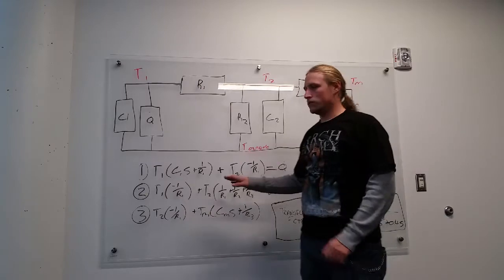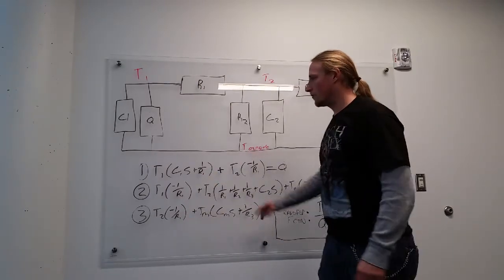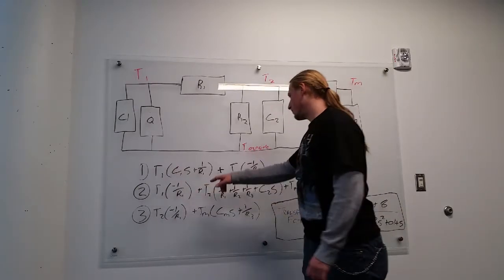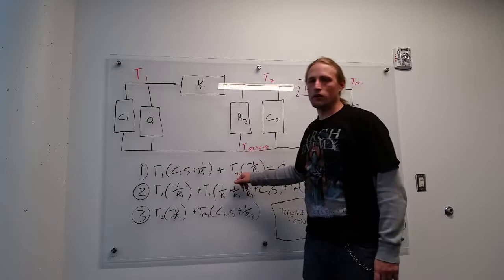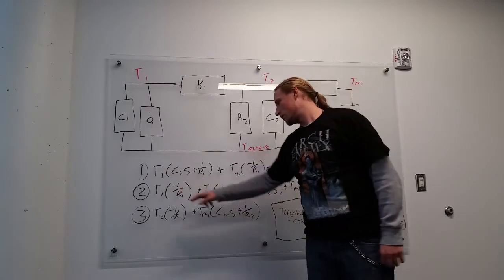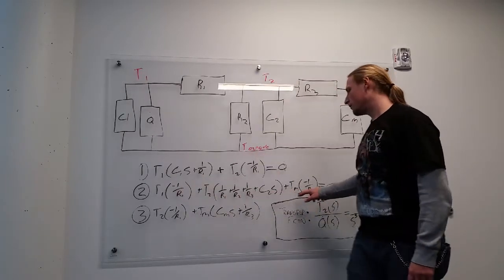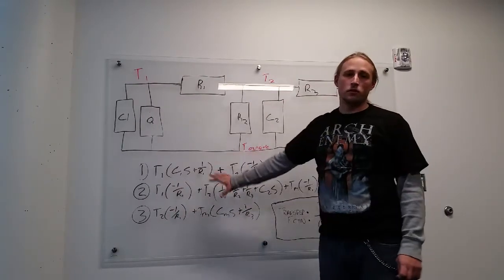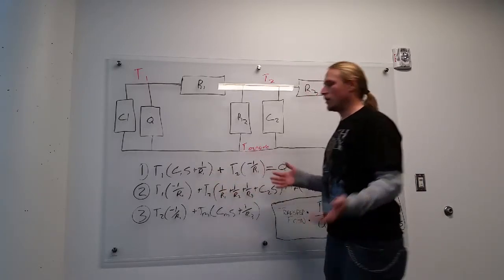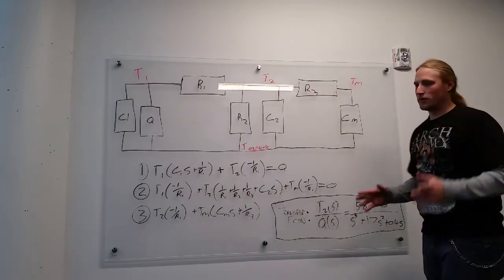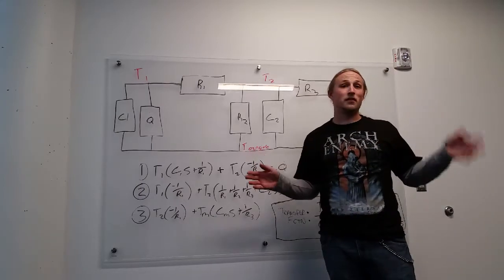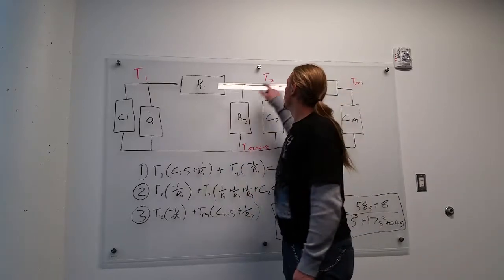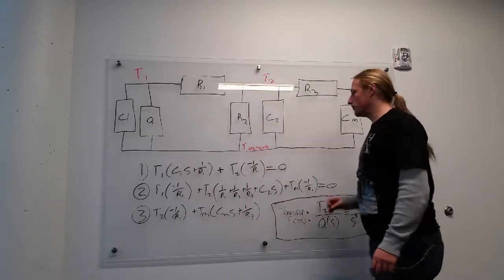And just basically using nodal analysis, we come up with these 3 equations here. For the first two, there are terms in T1 and T2, and for the third equation, T2 and Tm. Then solving this in MATLAB with matrices comes out with a really big function with big numbers in it for T2, the temperature that we're interested in.